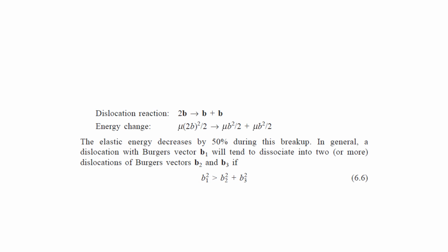Okay. Then the two incomplete planes are together on the slip plane, so that the Burger vector of this dislocation is 2b. But the two planes will have a tendency to break up into separate planes, to reduce the Burger's vector to b in each case, so that the 2b dislocation changes to two separate planes, and therefore the Burger's vector will be b and b. Therefore the energy changes.